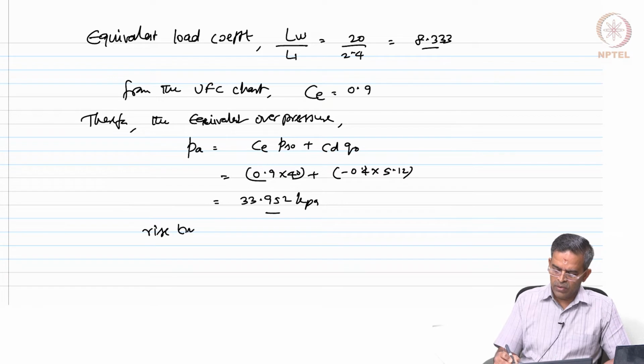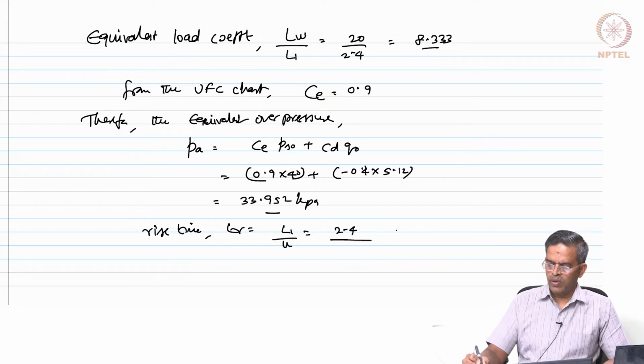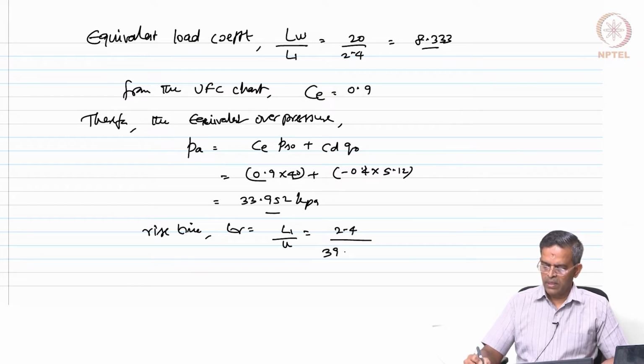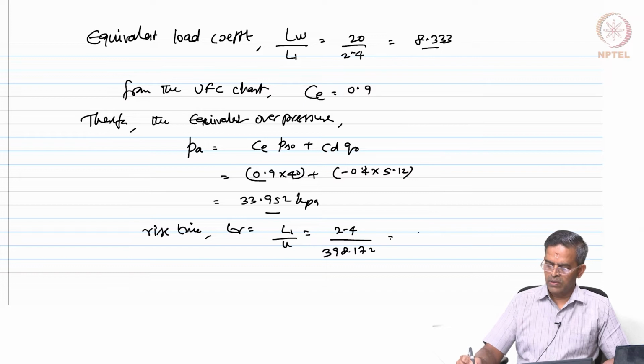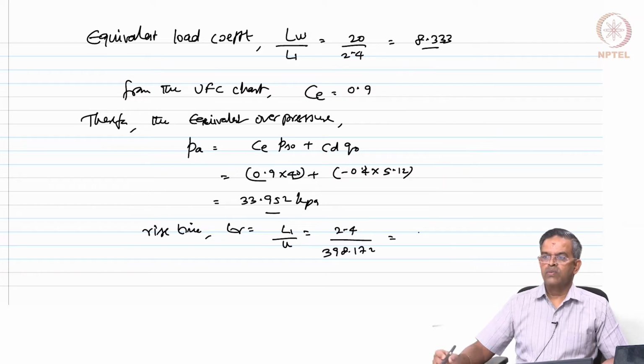The rise time for this TR will be L1 by U, which is 2.4 by 398.172, which comes to 0.006 seconds.